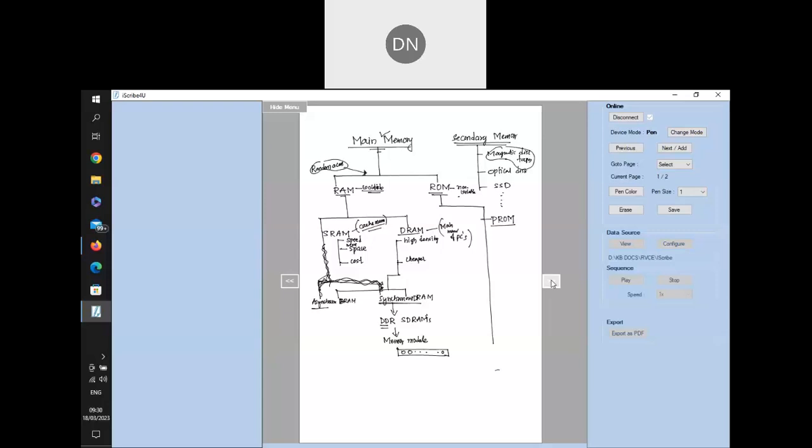When I say programmable read-only memory, at one shot, one time, I can write a program of my choice into the read-only memory. Either we can send that program to the manufacturer and he can do it at the factory itself, or once you get the chips, you can also do it. It's called programmable read-only memory. One time you can program it.